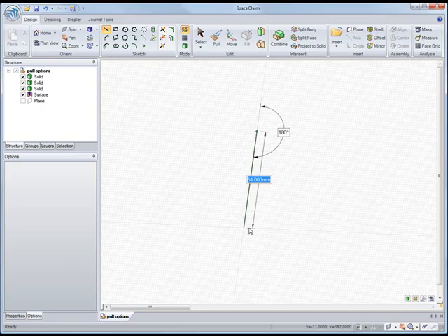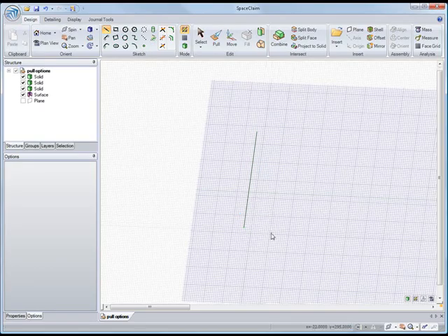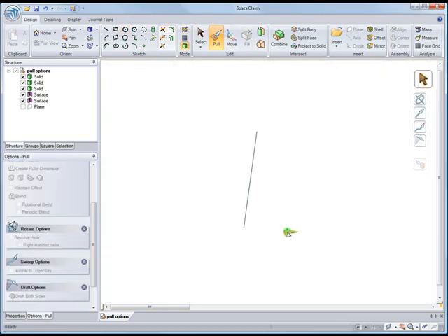And I'm going to sketch a line and sketch a circle. So now usually if you were going to rotate a circle about a line, you'd basically create a torus. So we'll choose the surface, choose our rotate option, and pick that line. And you can see that torus starts to be created. But our rotate option actually allows me to create a helix. So notice when I select that, we now have a height and a pitch that appears.